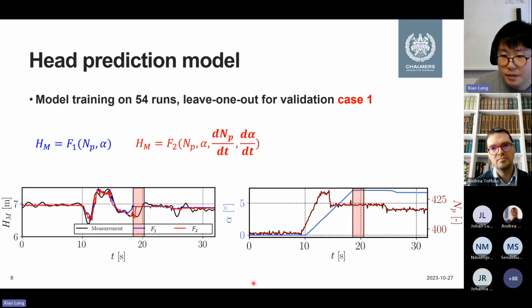The reason is that this happens just after the termination of the gate opening change, and this closed loop system is really sensitive. It needs some time to stabilize and recover from a saturation with the accelerating flow. But this phenomenon cannot be captured by the quasi-static model.